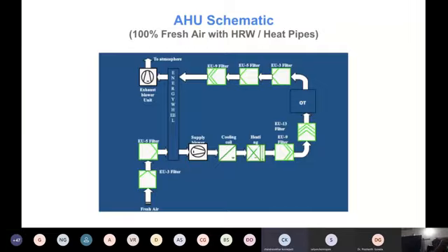So let's have a case study. When we talk about 4000 CFM, we have around 8.5 tons in the recirculation system. The same in fresh air goes to 15 tons, and all the 15 tons are evacuated completely. So we waste a lot of energy. We need the best system, but we also need to work out how to avoid the bigger recurring cost involved. So here it goes.